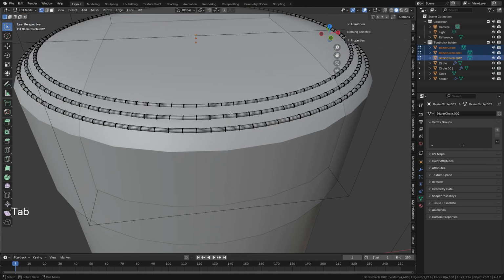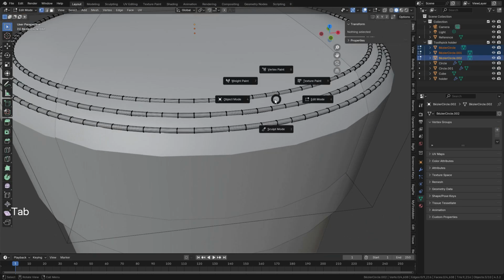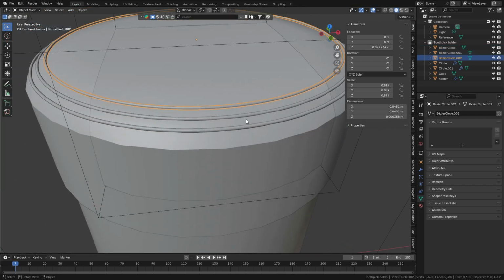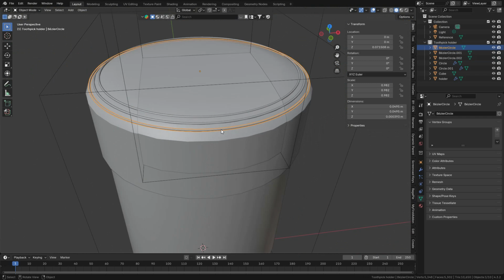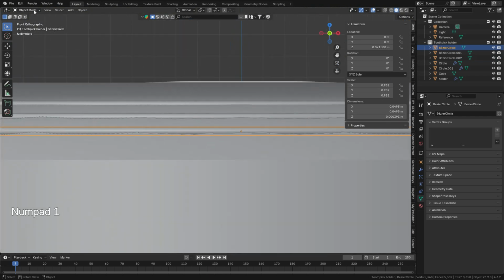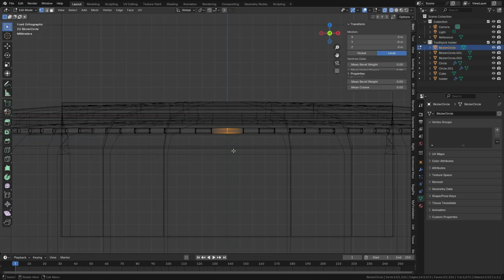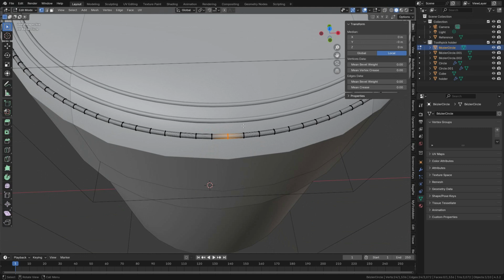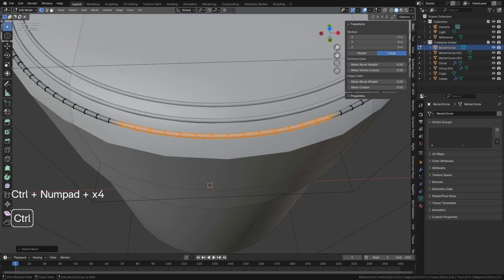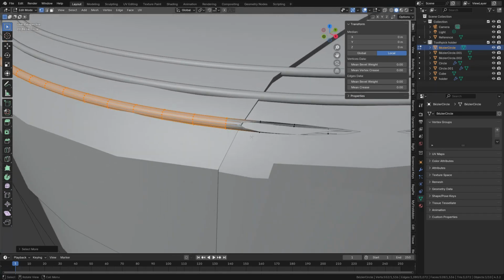So therefore when you press edit mode, you can see they are all vertices. Beautiful. Go back to object mode. So we're going to take our time doing this one by one. We start with this one here. Press 1, go to edit mode. Make sure you're in wireframe mode. Select this center which goes right through the Z. Go to solid mode. Then hit the keys Ctrl and plus to expand our selection. You do that again till the vertices meet near this edge. So do that. Okay, I think about here should be okay.